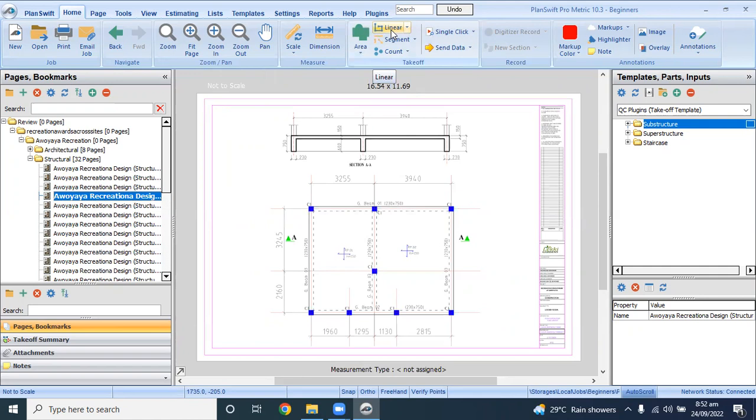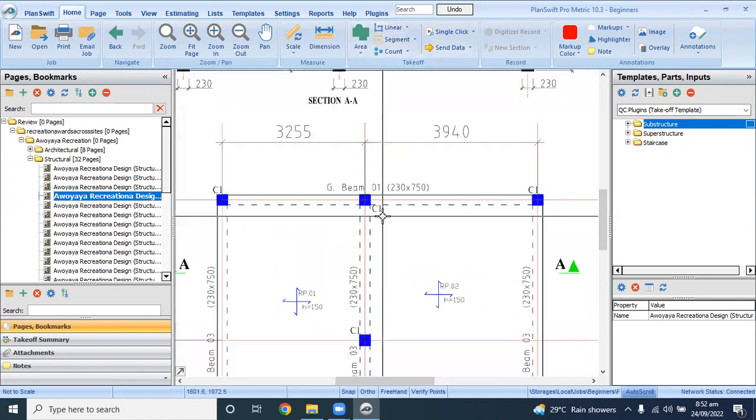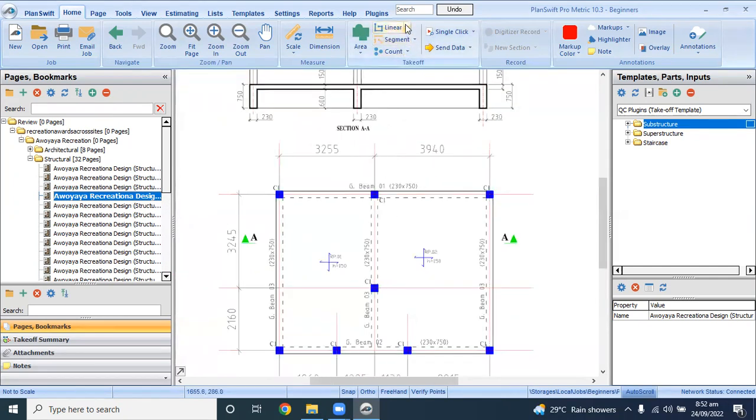You know that trench excavation is measured in cubic meters. So once you choose linear tools to measure the trench excavation, you have to manipulate the quantity you got in meters by multiplying by the width and the depth of the trench. Or another method: you can click by the side of this linear tool and click on linear cubic meters, because everything has been multiplied for you to have your unit in cubic meters. We are measuring for trench excavation.